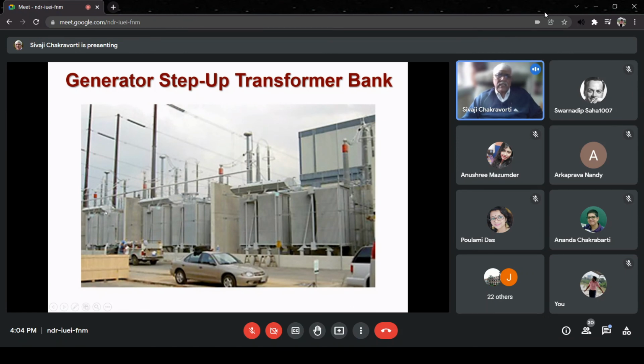So what we do, we can purchase 4 transformers of lower power rating and one transformer will remain connected to the line but not in power transmission, and 3 will operate in either star or delta. If we require one transformer for maintenance or one transformer gets faulty, then the 4th transformer will be immediately connected. As it is an external connection, there will be no problem.